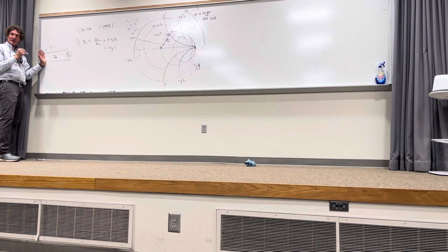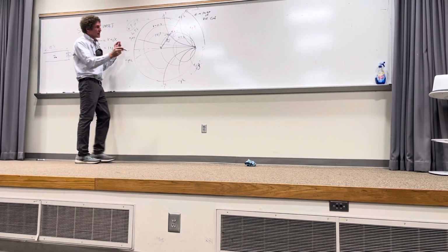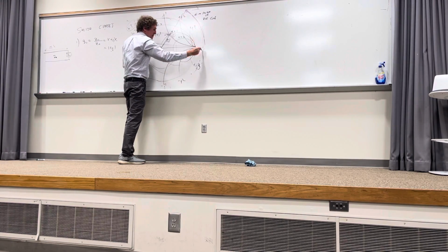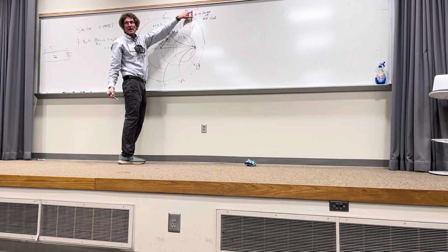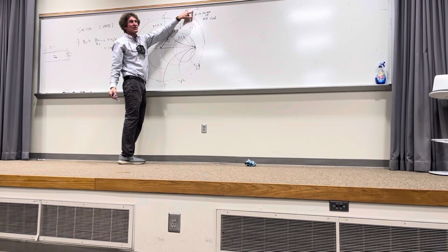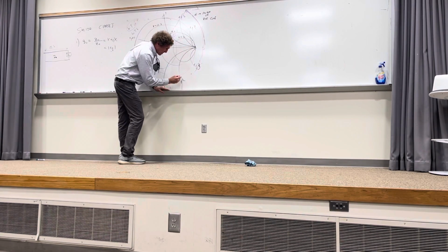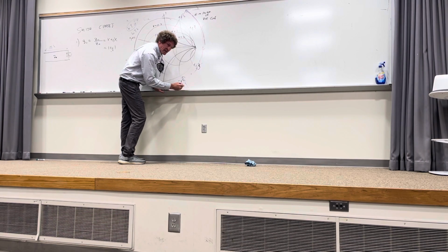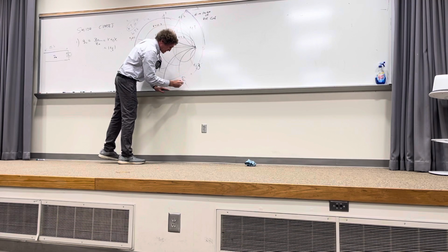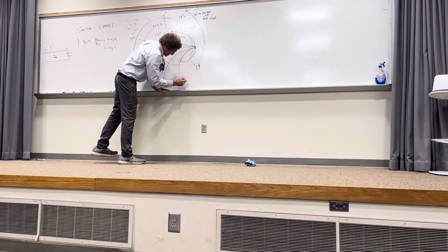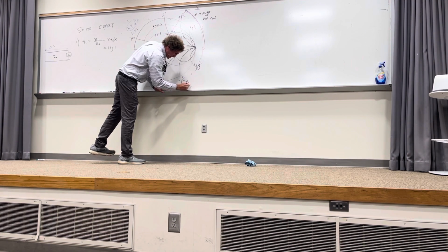Now just listen to this last segment, I'm going to let you go. So I come in here, then I move, I figure out how far I'd be. Say if this was 0.1 and I've got a 0.2 wavelengths long line. So I would find the marker where it was 0.3 wavelength. Y'all with me, class? I'm just adding it. So somewhere down here would be where the line length was added to this entry point. So this would be at generator. This is where the generator would be.